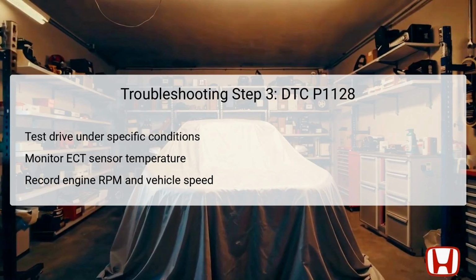The vehicle should be accelerated between 16 to 31 miles per hour, approximately 25 to 50 kilometers per hour, under half throttle to mimic typical driving conditions. This step is essential as it tests the MAP sensor's performance under load conditions and establishes whether it can adapt and relay appropriate signals back to the ECM.